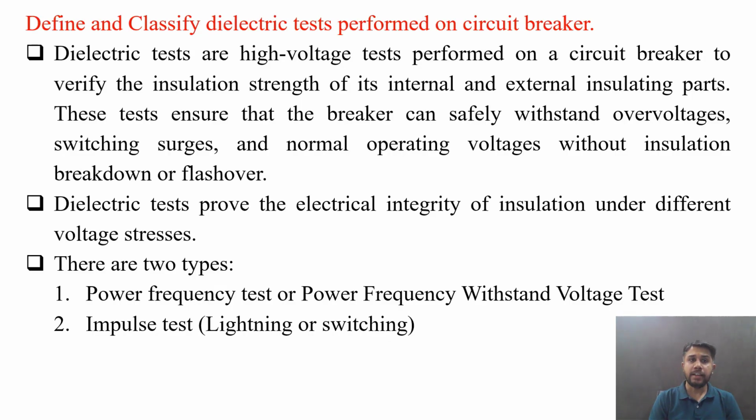Define and classify dielectric tests performed on circuit breaker. So dielectric tests are the high voltage tests performed on a circuit breaker to verify the insulation strength of its internal and external insulating parts. These tests ensure that the breaker can safely withstand overvoltages, switching surges and normal operating voltages without insulation breakdown or flashover. Dielectric tests prove the electrical integrity of insulation under different voltage stresses.